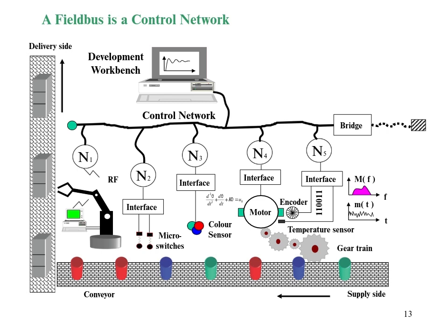What you see here, N1, N2, N3, N4, N5, these are actually the microcontrollers. They are connected to sensors at one end, and the other end is connected to the network. The difference between the centralized system and the distributed system is that you have only one networking system instead of one-to-one wiring. So you can save the cost.